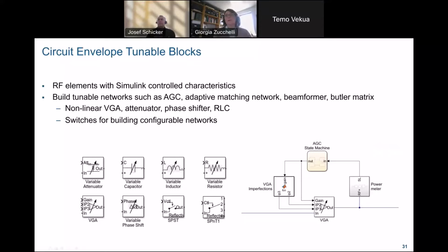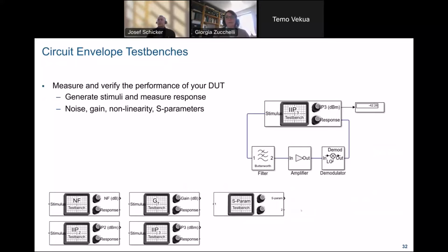And this block actually goes beyond that, because not only the gain changes instantaneously depending on the feedback or the output power, but also its nonlinear characteristics, such as the IP2 or the IP3, change as a function of the gain. So not only the gain, that is the desired effect, but also the function of the system.